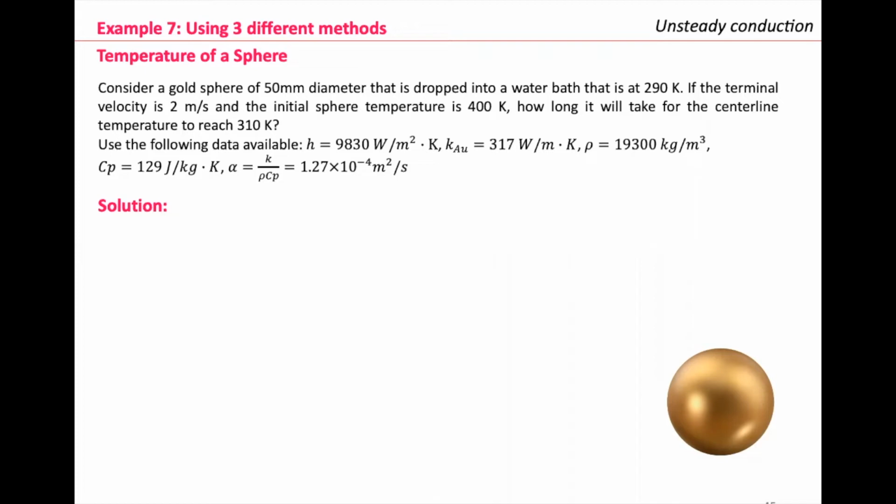Just be very careful. For example, I'm looking at your table 12, metallic elements, page 812 in your textbook. It's one of the appendices. The thermal diffusivity says alpha times 10 to the 6, okay? But this is an engineering table, so you read 10 to the minus 6. That's how you report the value. So that 10 to the 6, you use it as 10 to the minus 6 because this is an engineering table.